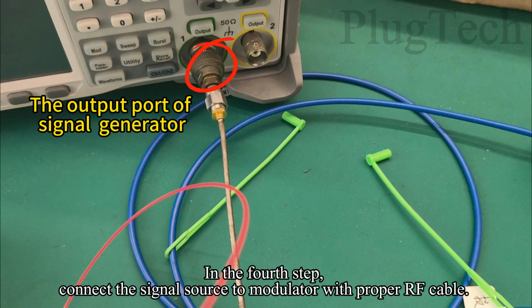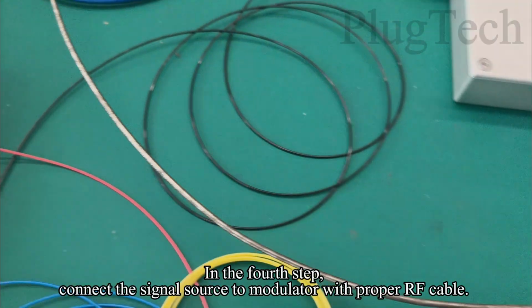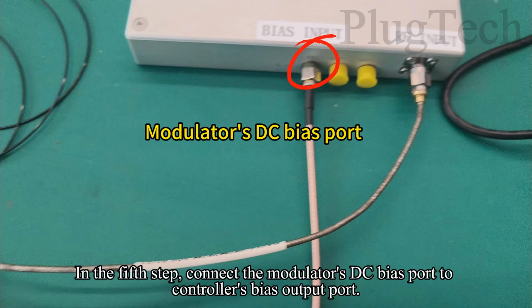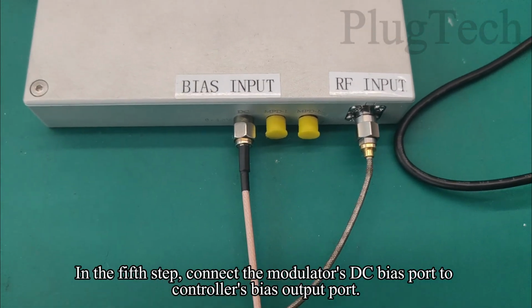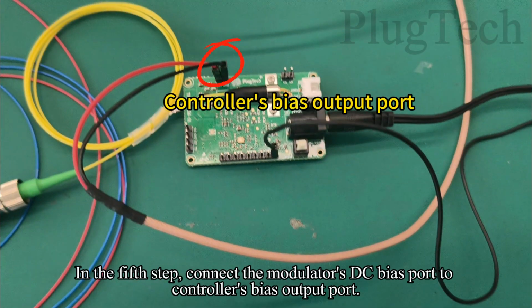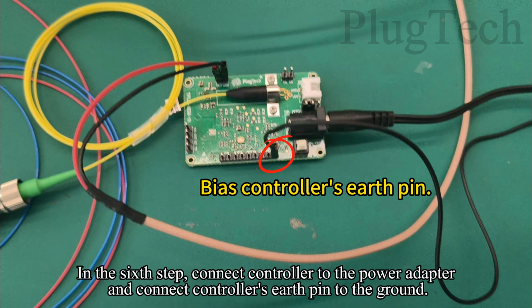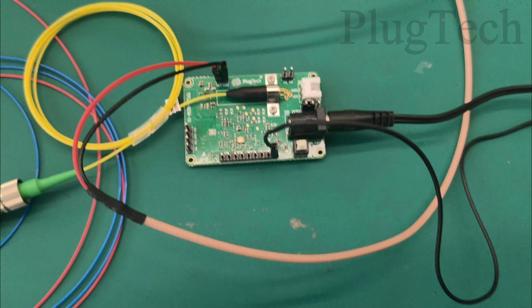In the fourth step, connect the signal source to the modulator with a proper RF cable. In the fifth step, connect the modulator's DC bias port to the controller's bias output port. In the sixth step, connect the controller to the power adapter and connect the controller's earth pin to the ground.